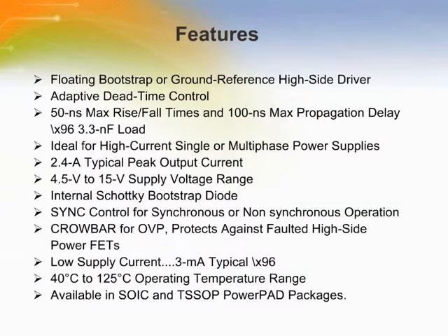The TPS2830 and TPS2831 are MOSFET drivers for synchronous buck power stages. These devices are ideal for designing a high-performance power supply using switching controllers that do not have MOSFET drivers. The drivers are designed to deliver 2.4 amp peak currents into large capacitive loads. The high side driver can be configured as a ground reference driver or as a floating bootstrap driver.